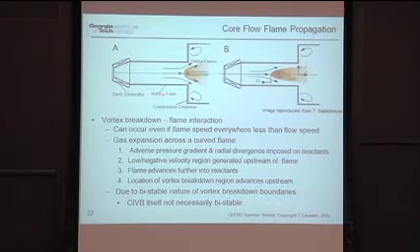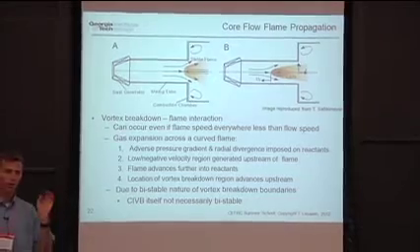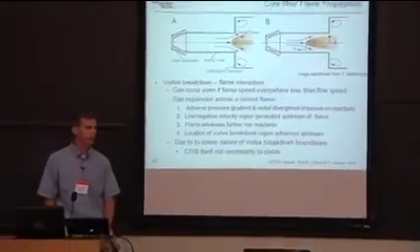Swirl flows don't like adverse pressure gradients. They want to break down. So what happens is the flow breaks down. So now I have reverse flow. So the flame starts moving back. As it moves back, it causes the approach flow to break down. And so that vortex breakdown bubble just marches upstream, and the flame just merrily follows it back. So basically, the flow sucks the flame back into the nozzle. So again, on average, the flow velocity is greater than the flame speed. But locally, it's not.